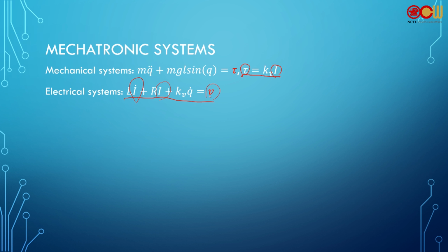In other words, the voltage you provide equals the inductance times the time derivative of the current, plus R i, plus a term with the angular velocity of the motor. So it's a tricky equation because it not only depends on i dot but also on the mechanical system q dot. So we usually consider this as the outer loop. You can apply PID in here. In fact, you have another inner loop that is used to control current.